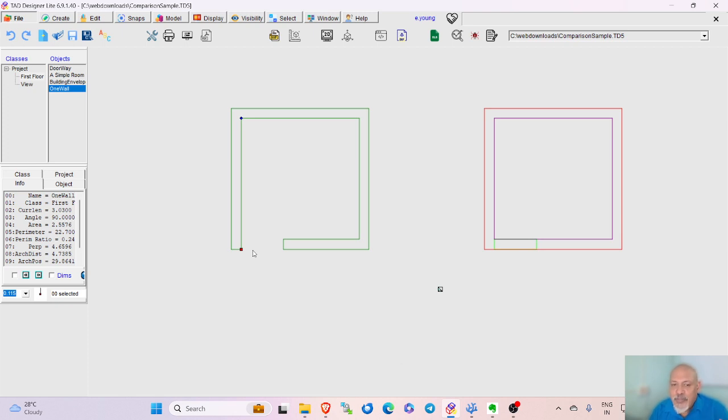Now, people do this pretty fast, and when they do it fast, they don't realize that it is because of their activity that the computer came to know about the area of that room. The computer has absolutely no clue whatsoever. There is nothing inside that particular CAD file which actually defines that room. On the other hand, the computer definitely knows the thickness of the wall, and the computer can be made to get the area of that wall. That it knows pretty well.